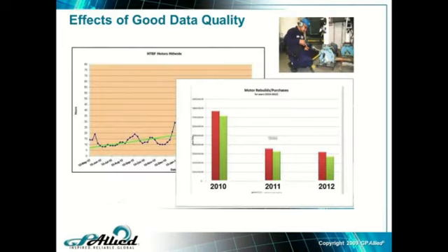Now the effects of good quality data. So we have good data. We're looking at mean time between failure. This chart, motor MTBF, motors mill wide, is actually a real chart over 2 years. And you look to the right, you see they're using ultrasound lubrication. I tell you, this is the only thing they did. It was 900 electric motors, and here's the results of it.